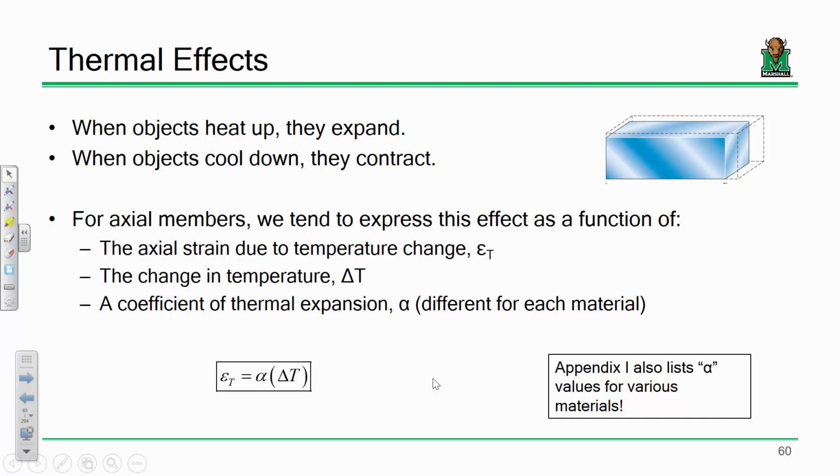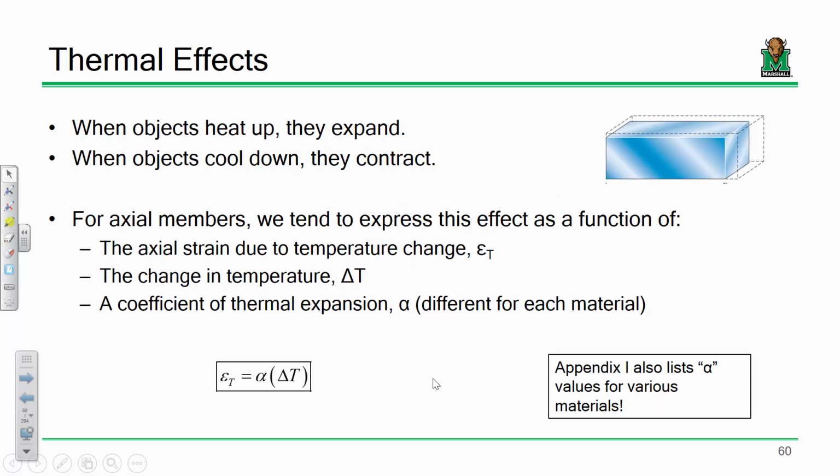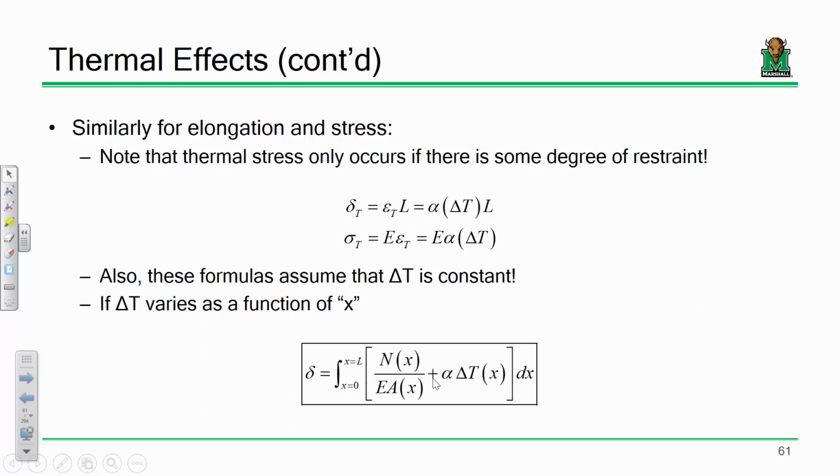So I have here just a box, okay? And let's say I've got this box and I heat it up, okay? If I heat it up, it's going to expand. And of course, it's going to make it larger. So I propose that that box is going to undergo some degree of thermal strain, okay? But the question is, is it going to undergo stress? Is it going to be a force per unit area? Well, I propose that for that box there on the top right, the answer is no. It's not going to undergo any thermal stress at all. It's going to undergo strain, but no stress.